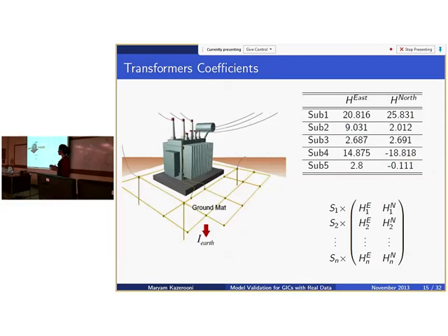To account for this inaccuracy, we assign some scales to each of the substations, and we multiply these scales by the coefficients. These scales are associated with the ratio of the actual grounding resistance to the grounding resistance which we had available and was not accurate.